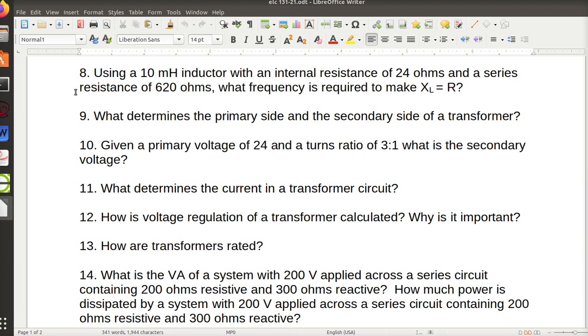Most transformers are stamped with high voltage, low voltage, or the voltage ratio of the two sides, which is the same as the turns ratio. And they do that to make it easier. So if you buy a 480 to 120, you know that if you put 480 in, you'll get 120 out. They don't have a 4 to 1 ratio and make you do math, but they could.